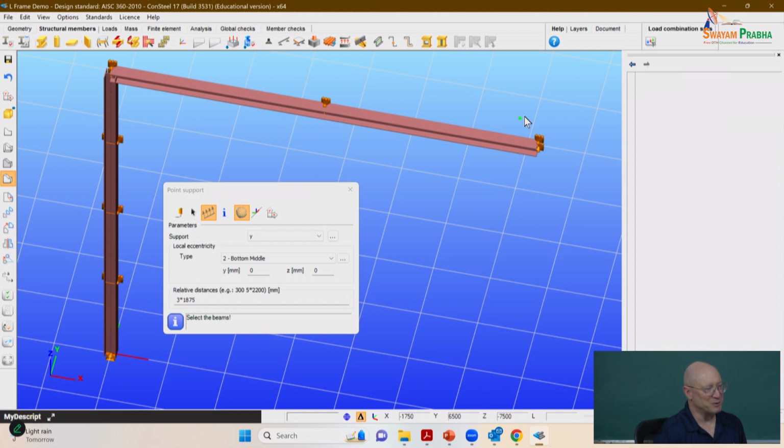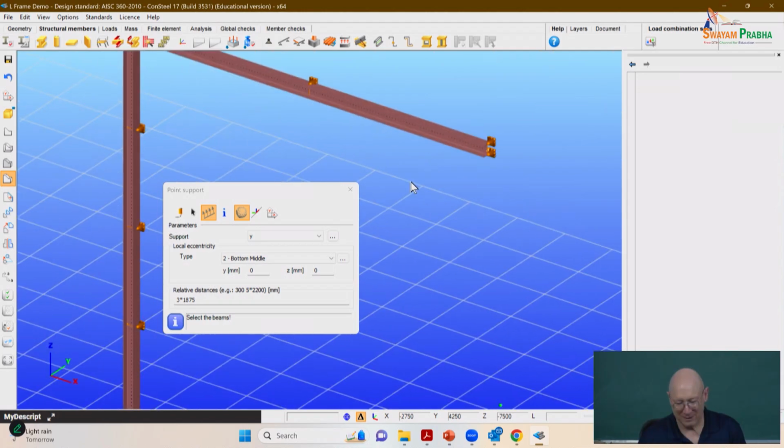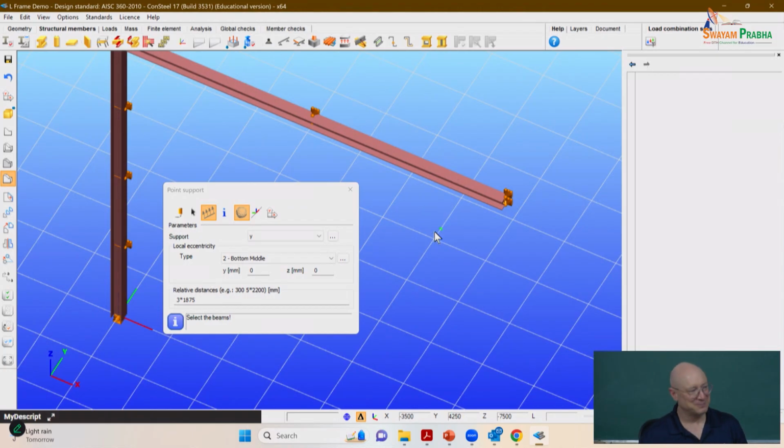So it has the smarts, so if I told it to use 4 elements, and I say, oh, but I want some other boundary conditions, it's going to say, oh, okay, so I'm going to have to use some more. Irrespective of whether it's a node or not. Correct. So that's good because your structural stability doesn't dictate the finite element efficiency. Correct. And generally, it's the other way. As a rule, I think they have heuristics where if you leave it on automatic, they automatically put in a mesh that usually works pretty good, but then you can control it manually.